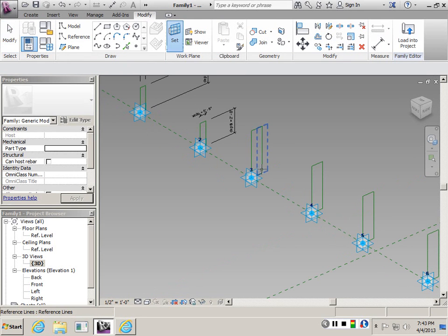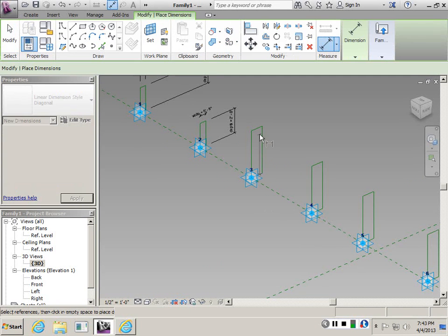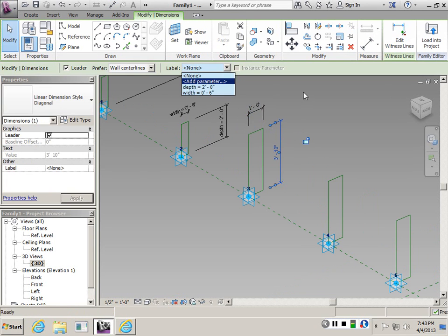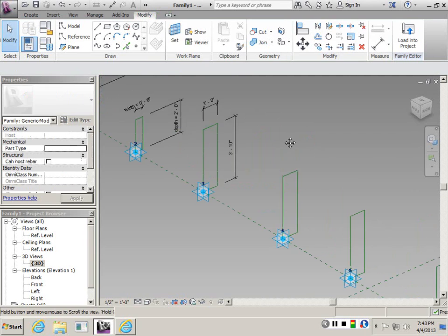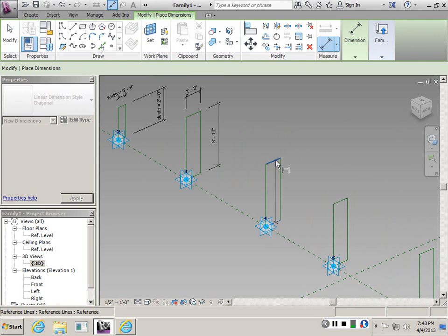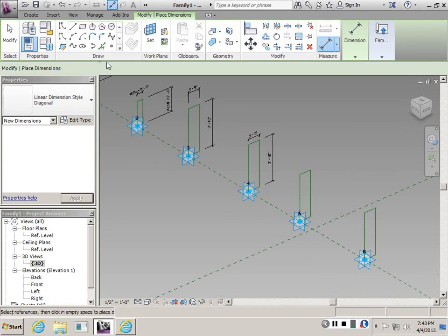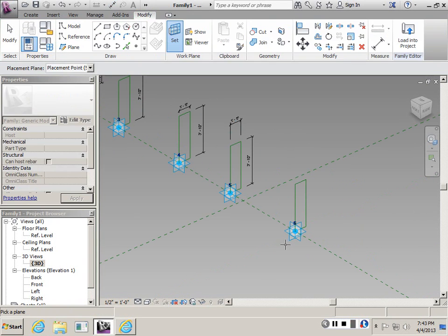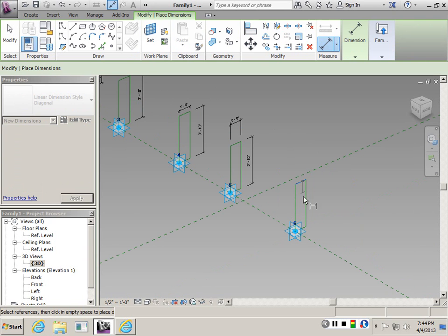So again, set, go to the third one, annotations, vertical and horizontal, and this one is going to be depth. Actually I can set up those afterwards. So let's go to the fourth one, annotations, set fifth one. It actually recognizes the last tool that I've used if I use it in an order. So I don't have to click on annotations actually. I can just click on the set work plane and it brings in the last function.